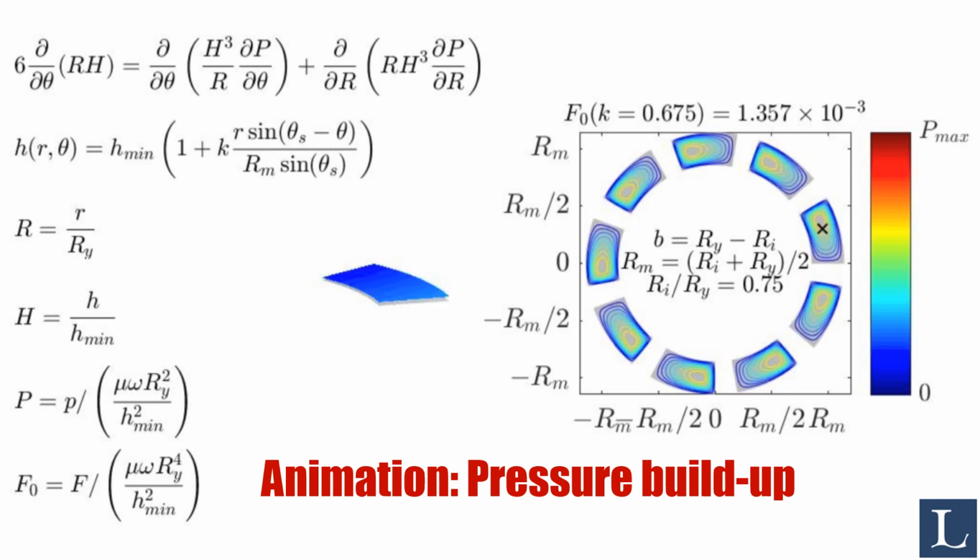What you perhaps did not notice was that as the inclination increased, we reached a maximum and then it decreased again. A maximum for the load carrying capacity in terms of its dimensionless quantity, F naught. So you can see that the maximum is somewhere around 155 or so, and it occurs for about K equal 1.5. And this is matching the design chart graphs that we saw before also.